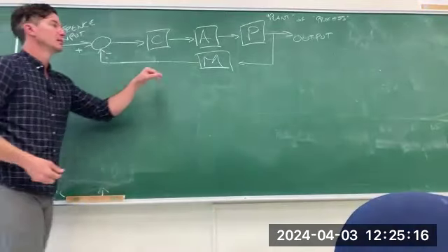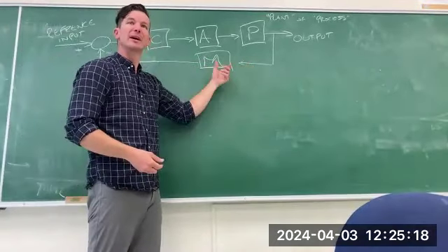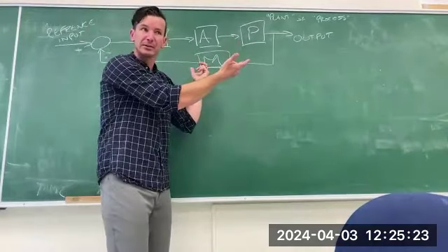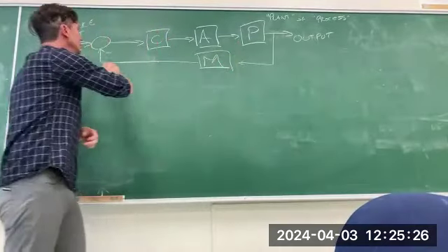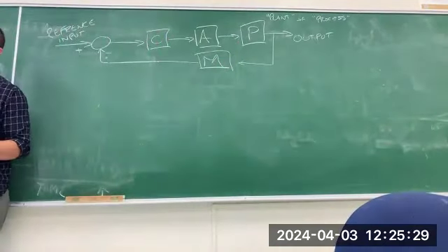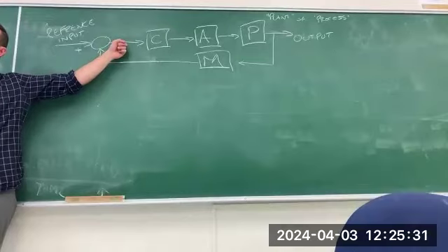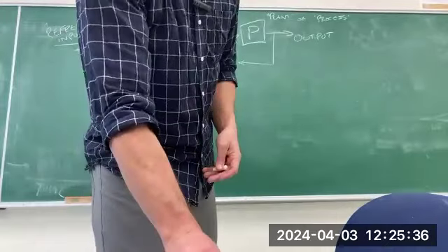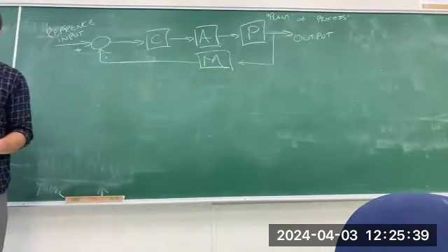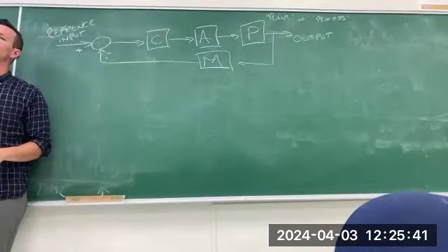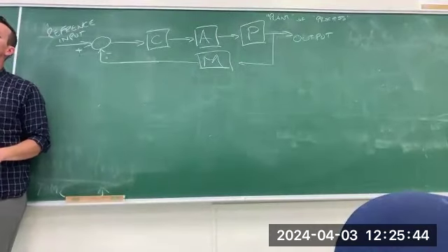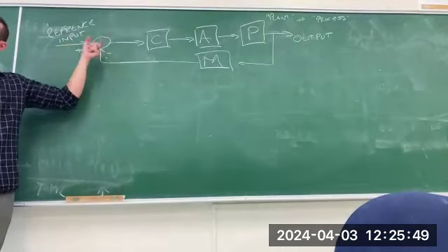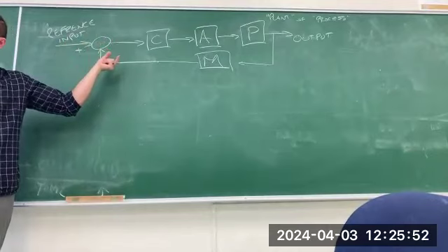We're taking something that should be the output, right? If your measurement device is perfect, then this is exactly that, just with different units. We're taking the output and subtracting it from the reference. What name would you give this signal? Difference? Error is what I was looking for. What you want minus what you have, that difference is how wrong the output is.